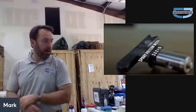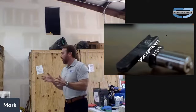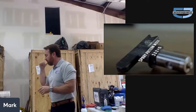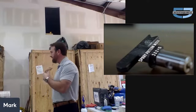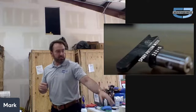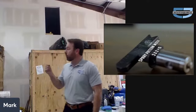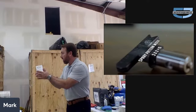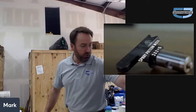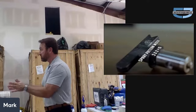All right, tips. Tips are rated kind of like the tips that we talked about with pump sprayers and BTM and things of that nature. Similar type of thing here. So this tip right here, you can see, is a 311. The 3 is your width. In this case, you take the 3, multiply it by 2, and it gives you 6, and that means 12 inches from the surface, you're going to get 6 inches of coverage.